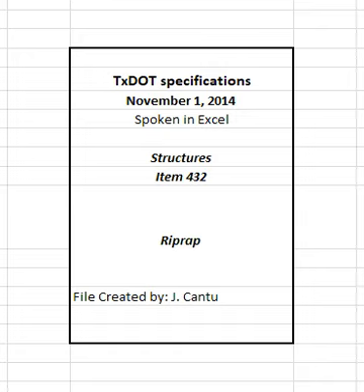3.2.2.3 Mortaring. Construct riprap as shown in Figure 2 on the stone riprap standard. Lap courses as described for dry placement. Wet the stones thoroughly before placing mortar. Bed the larger stones in fresh mortar as they are being placed and shove adjacent stones into contact with one another. Spread excess mortar forced out during placement of the stones uniformly over them to fill all voids completely. Point up all joints roughly either with flush joints or shallow, smooth rake joints as directed.